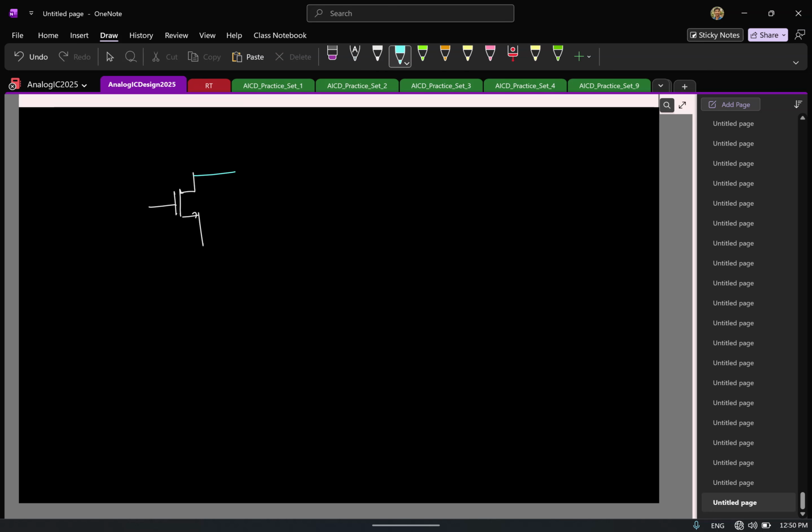We assume a current source is added, direction doesn't matter. For simplicity, let's assume the source is grounded. I'm interested in modeling the noise using an input referred quantity. Do I need both input referred noise voltage and noise current, or is one sufficient?